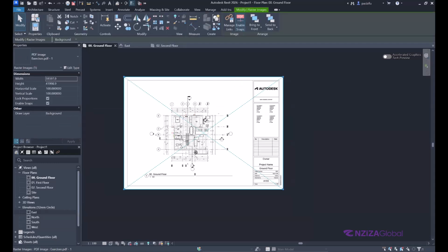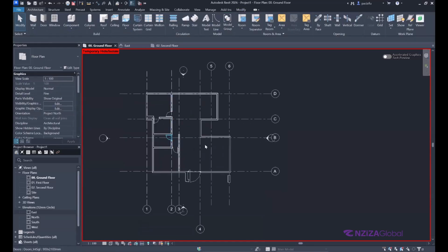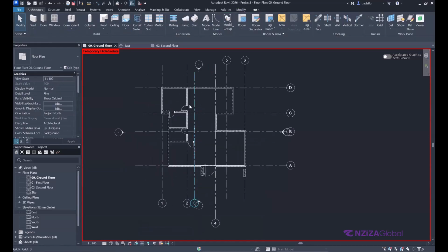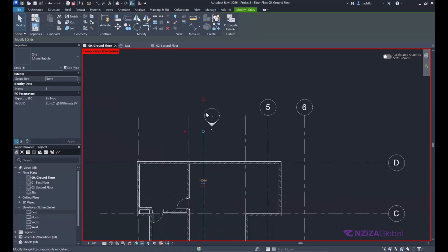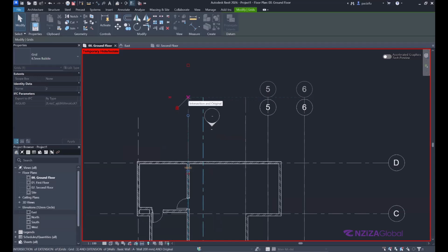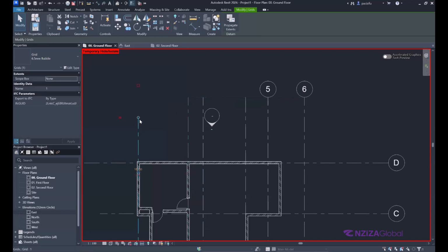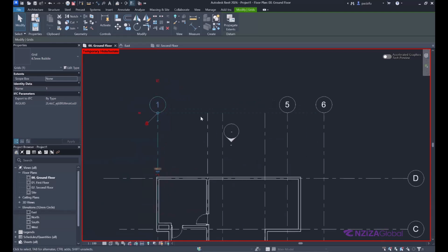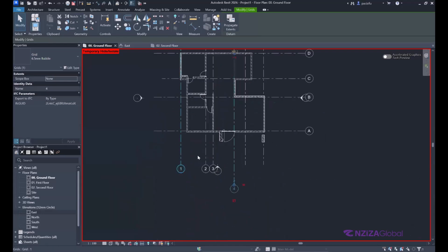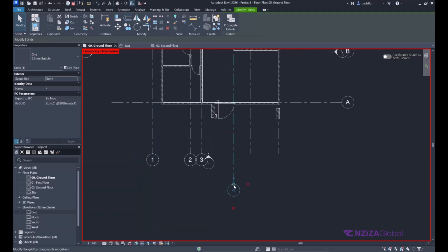So if I temporarily hide this PDF, I have my grid there. I need to align them very well. I will just take this, and if I bring this up, it will show me that it is going to be connected on the top level of this. Even this to be connected with this. Then I will activate those numbering up here. Then I can deactivate them down here.